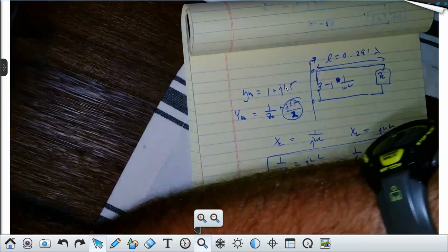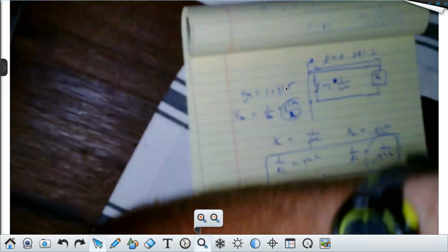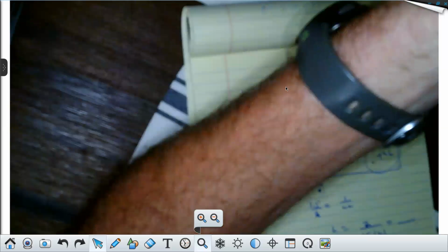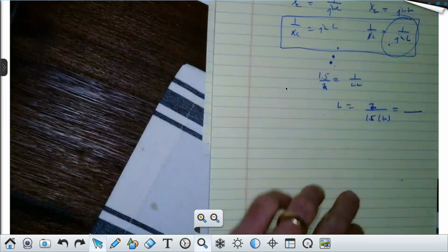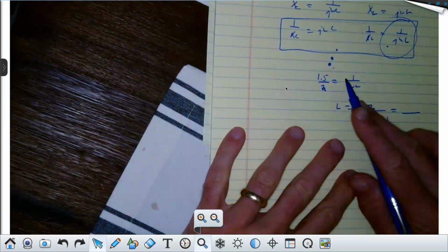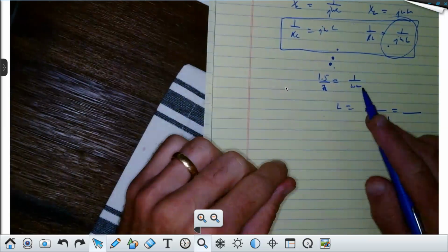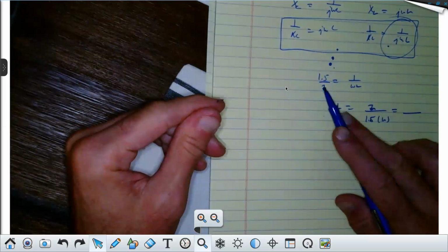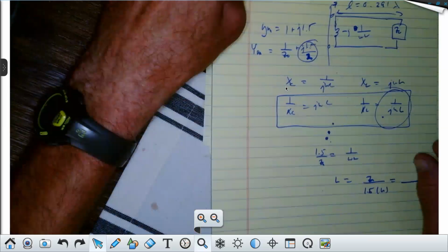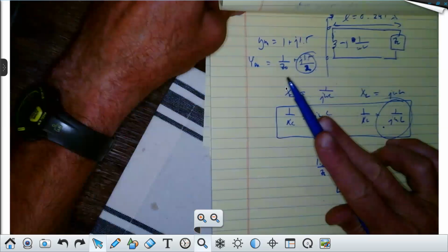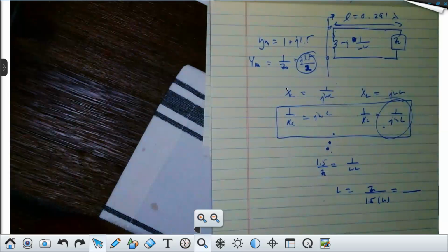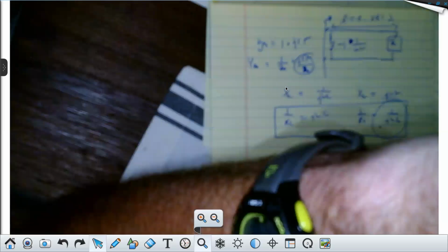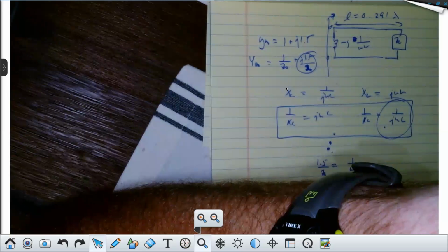It's just like impedance matching in series, but we're putting things in parallel. So we're in the admittance domain. The admittance of an inductor is 1 over J omega L. It has to be equal to 1.5 over Z naught, because that's the value I'm trying to get rid of. So I'm left with just an input admittance of 1 over Z naught, which would mean the input impedance would be Z naught. And that means I would have the reflection coefficient of 0. Everybody follow me, class? Give me a thumbs up.